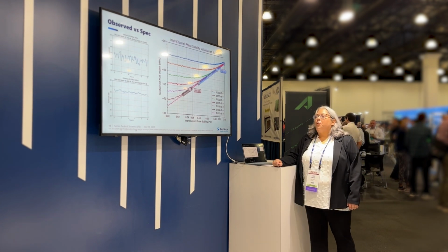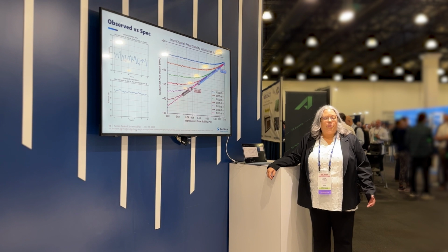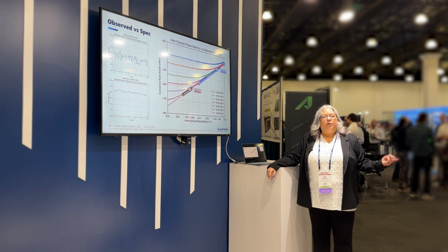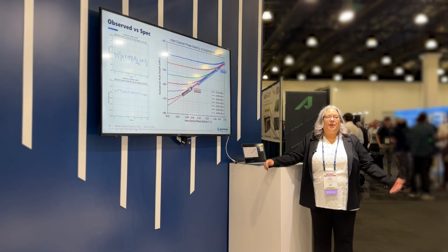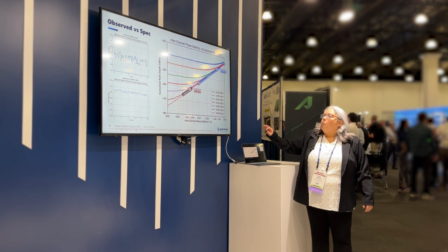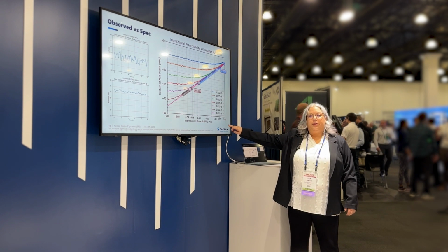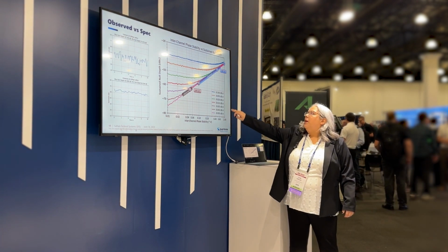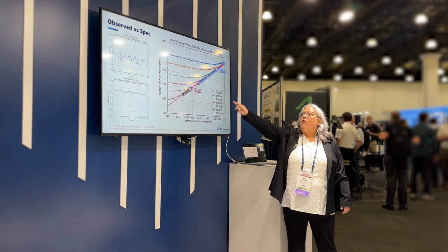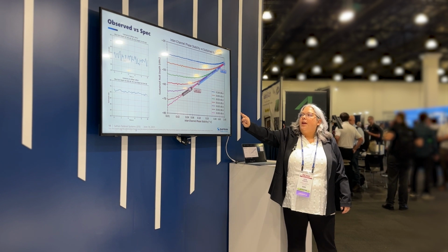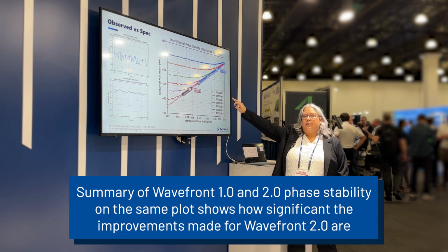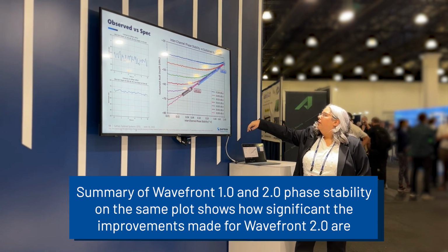And finally, this is kind of a summary of all of this with the phase stability. Again, with phase stability we're really looking at the stability of a single signal, but for our testing we have to use two signals, two different elements, because we want to be able to create the null. That's why we say interchannel phase stability. But it's that same image we looked at earlier for the 2.0 measurement, and we can also now plot these graphs on there, like what the internal LO was and what the external LO is for typical and max values.